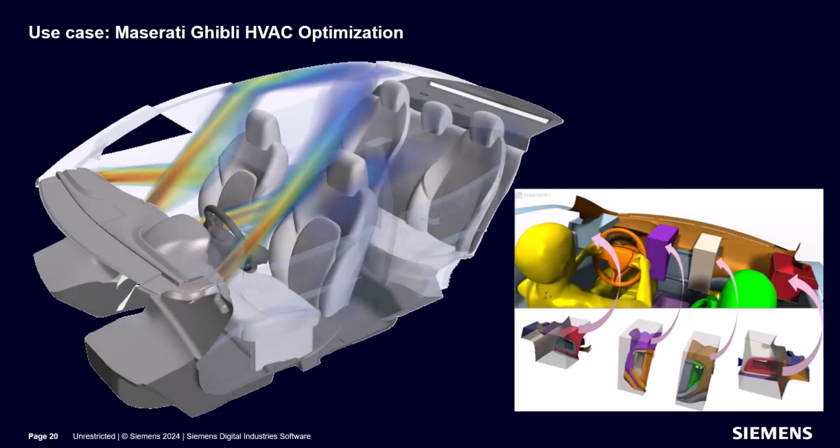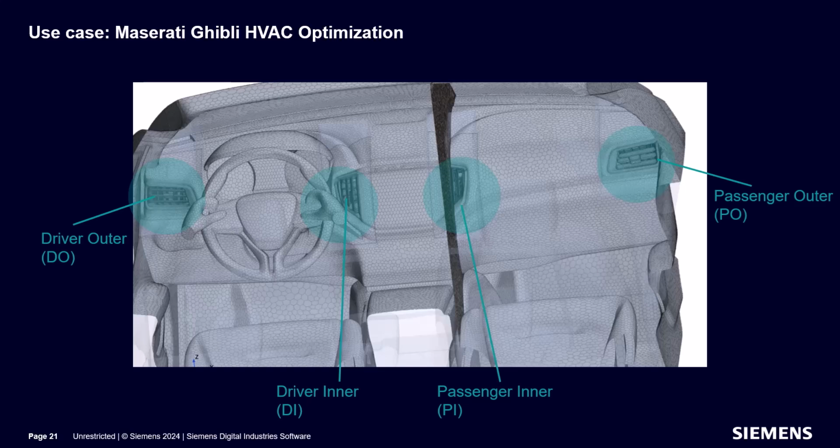To demonstrate the power of the response dependency feature, we will look at a computational fluid dynamics example. Specifically, we will look at an example that from the practical sense most will relate to. We have an automobile where we are looking to maximize the performance of an HVAC system. Notably, we'd like to get as much airflow to key passenger locations in the vehicle to maximize the heating or cooling experience for passengers. As such, we are presented with the question, how to best orient the vent deflectors to maximize the velocity field at 4 target zones.